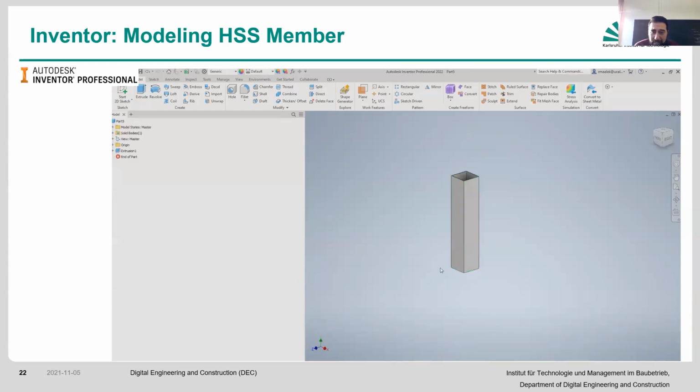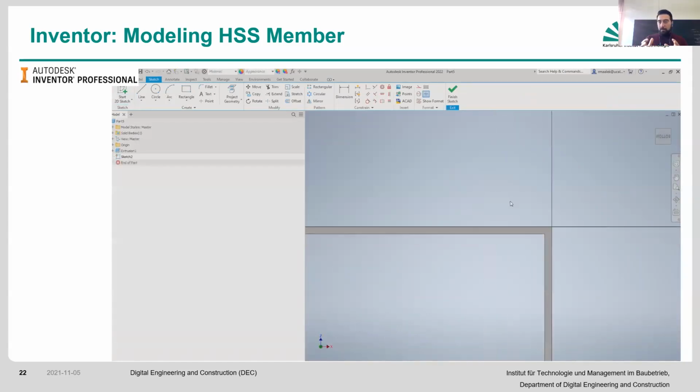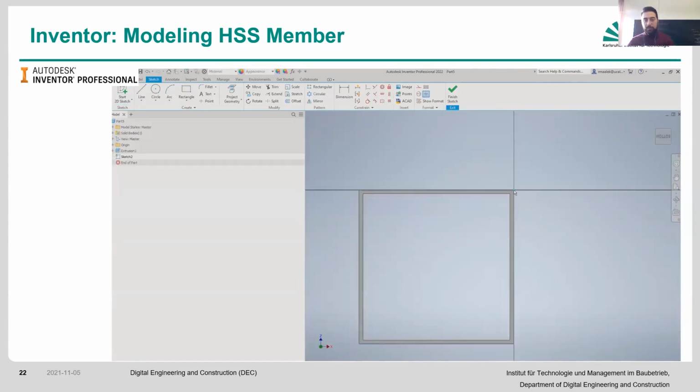Once you perform that, it's always customary for these types of analysis to also create, let's say, some sort of small base underneath to provide you with the option of being able to connect it together in a fixed way, which is again our ideal assumption there. So what I'm going to do, again underneath this whole thing, is have another 2 centimeter rectangle underneath.